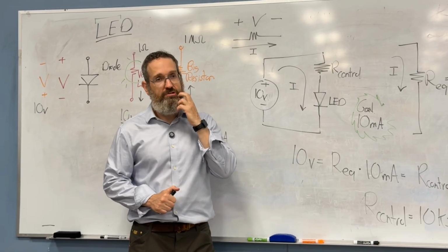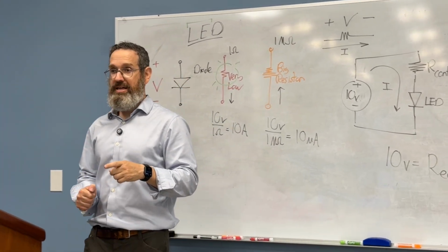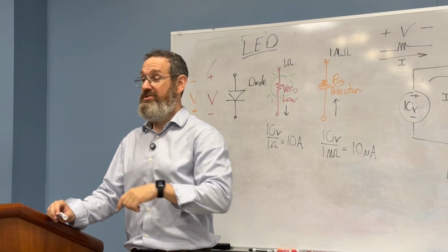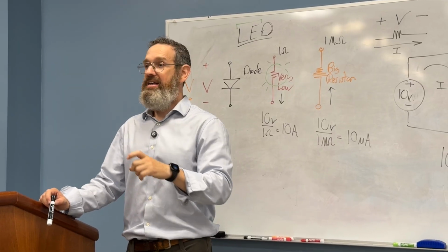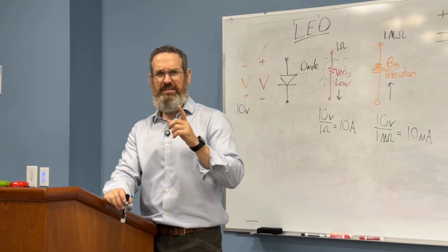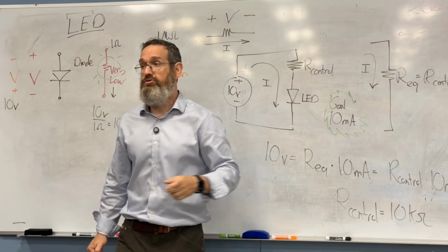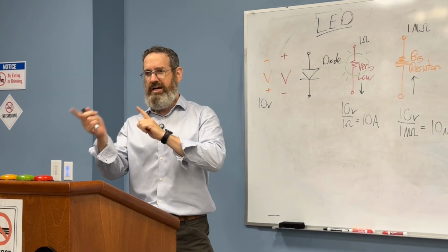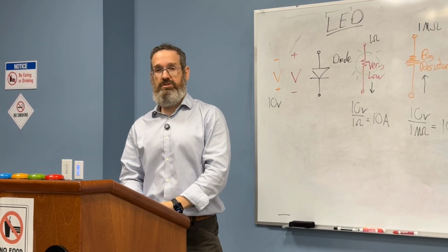And that's where we're going to stop for today. Your next lab, by the way, is you have to turn on a light that corresponds to the temperature of the jar. So if the jar is 25 degrees, a red light has to go on. And if the jar is 30 degrees, a green light has to go on. Now that's a little bit interesting, but I've given you the first piece of this because I've shown you how to turn lights on. But now you have another question, how do I decide which light goes on? And that will be covered next class with a circuit called a comparator.